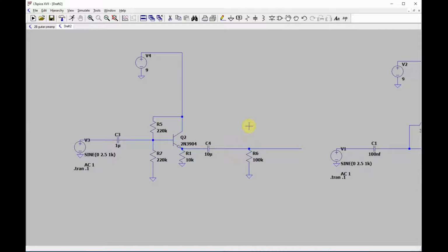so how you're supposed to, and why do you want this to be way larger than this? Well, it's because you don't want this bias affected. This is part of the reason. See, you're using these 2 resistors to set this value right in the middle. So if you put something that competes with this one, it drags that down.